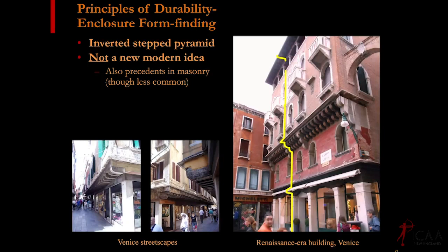So here they were cantilevering out and making masonry buildings do this. Obviously, that's not easy. And in some cases, they're doing it with stone corbels. And in some cases, they're actually doing it with wood. So you see that here and here. And these are just very average run-of-the-mill buildings in Venice. I think this is a particularly beautiful example where the floor joists come through. And then where they have a demising wall and hence greater load because of the load of the masonry, they put in these beefy travertine corbels. And then also big roof overhang here.